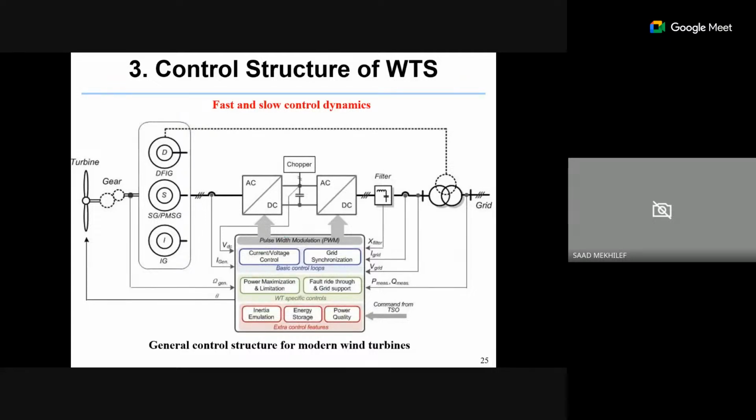But you can see, if it is fully power electronics or converter driven wind turbines, it all goes back to these converters' PWM control that's generated in terms of grid synchronization, voltage, frequency, and current control. Even, like I mentioned just now, the MPPT, the inertia emulations, energy storage.